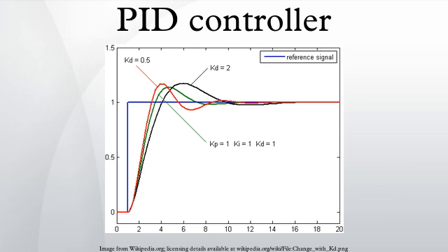In this example, two variables that will be maintained within the loop are initialized to 0, then the loop begins. The current error is calculated by subtracting the measured value from the current set point. Then, integral and derivative values are calculated and these and the error are combined with three preset gain terms, the proportional gain, the integral gain and the derivative gain, to derive an output value.